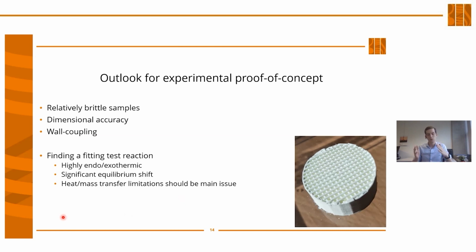So we saw before that we can make the gas really swirl from side to side within the structure. But as you can see, the structure has its own small wall on the side, which acts as a heat transfer barrier. And especially if this wall doesn't perfectly touch the metal reactor wall that we use in the lab, the heat transfer is not so optimal. So this is something that is really, really difficult to optimize.